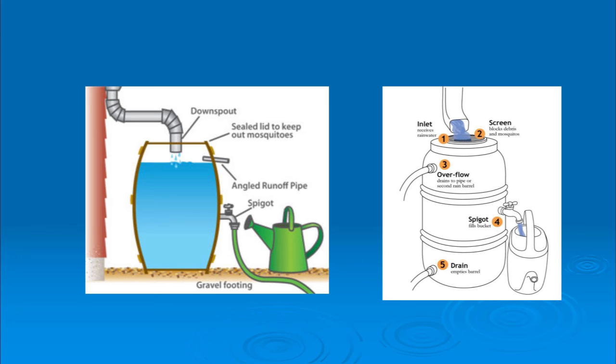Same resources with rain gardens. Feel free to look around, and if you ever have any questions, the basic design's always the same. A lot of them I've seen now don't have stone. I like that stone because it's great for storing water temporarily. It gives you more capacity. But I really like that mix of sand, compost, and topsoil. It's great for your plants anyway, and it has large pore spaces, which allow the water to run right through and get into the groundwater.